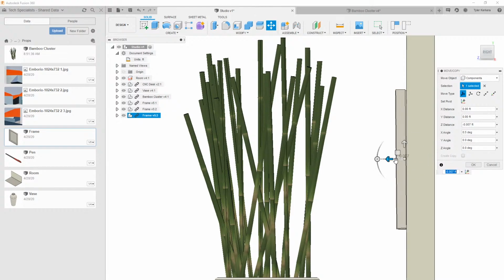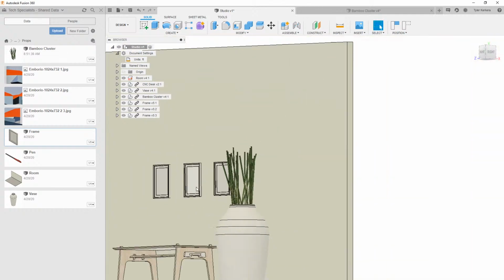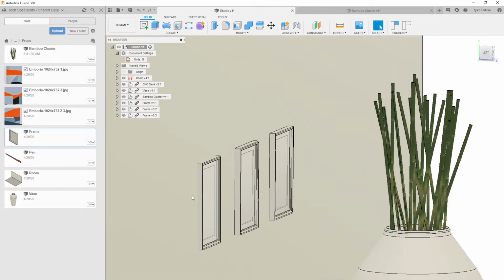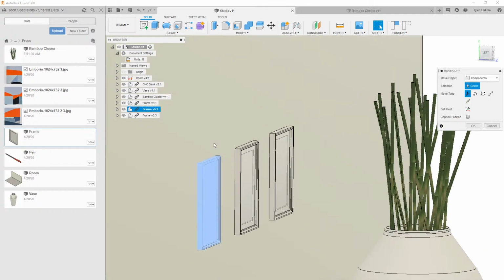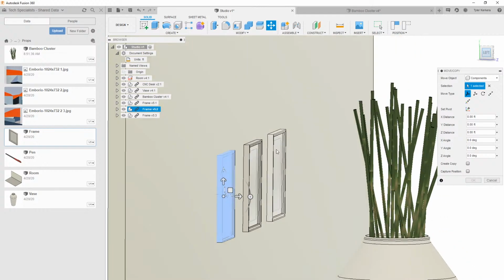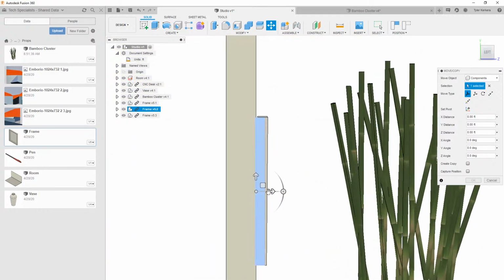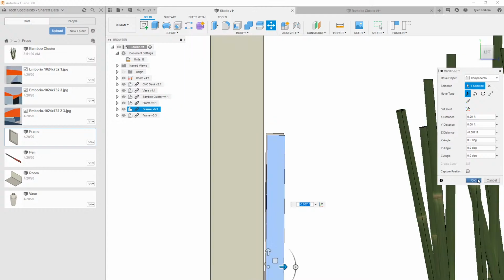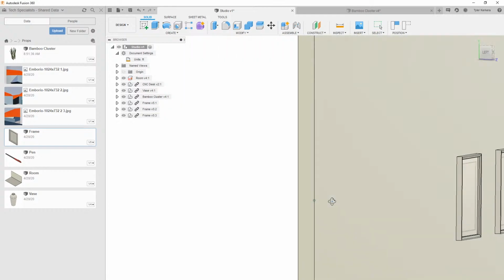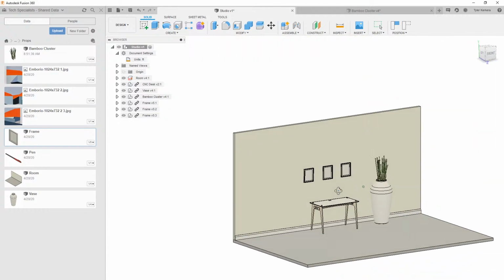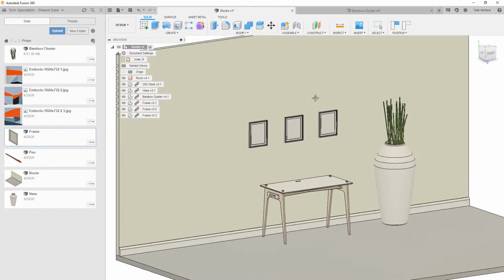And we're going to replicate exactly what we did with these other ones over here. Let's grab this guy, do that same thing. Again, I'm just pressing M on my keyboard to move it. That's allowing me to do exactly what I want here. We want that 1/2 degree that we used on all of them. Here you can kind of see the imperfections in the height, and again, I kind of like that. So leave that how it is. So that's looking pretty good.